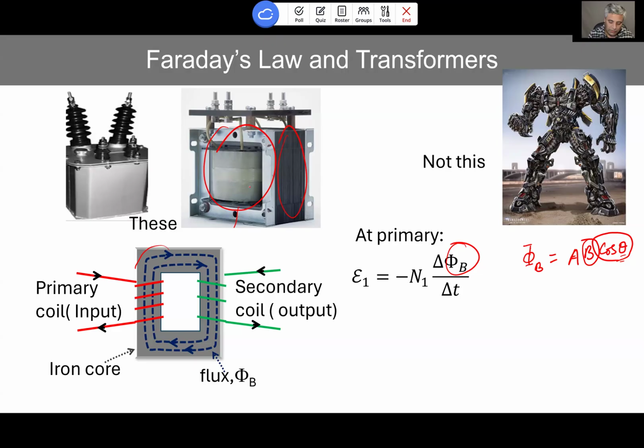So now what happens is with the coil on one side, when we pass current through it, it induces that magnetic field. So basically, it generates the magnetic field, I should say. So the current flowing through the coil acts like a magnet, right? But the magnetic field in such a coil, which we also call a solenoid, is given by this equation. So for a given coil, the number density of the coil is fixed. This constant is fixed. So that means you can change the magnetic field only by changing the current. Okay. So if you are using direct current, that means the value changes only when it turns on and off. That's it. So other than that brief moment, there is not going to be any induction.